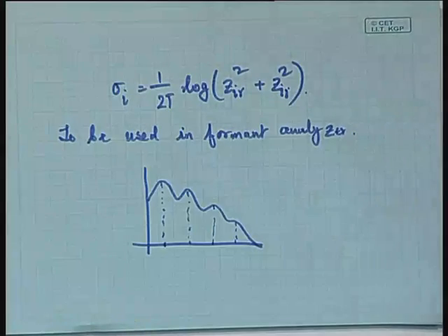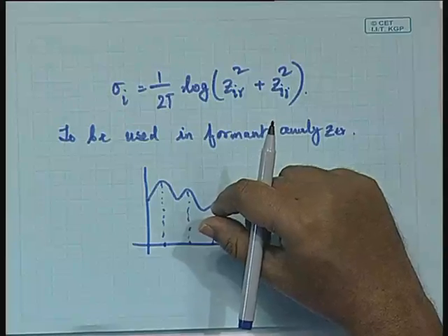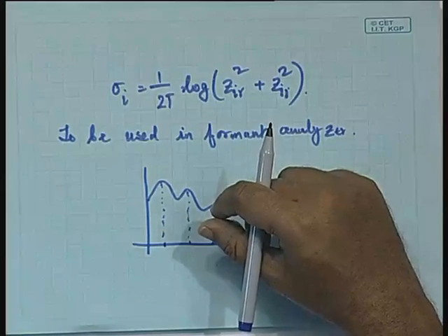From these roots, it should be possible for us to obtain the central frequency and also the bandwidth of the individual formants. In fact the roots may be obtained quite accurately, so using these roots we should be able to model the formants.